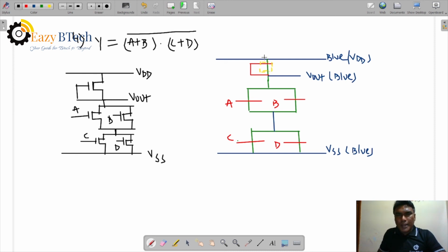Now let us take the contact area. Here is the interconnection point. Here also polysilicon and metal is an interconnection point. Both diffusions are interconnected. Metal and diffusion here, metal and diffusion over here in the series connection, and here also metal and diffusion. The ground metal and diffusion is here. So these are the logic. As per the logic, you can draw the circuit diagram in NMOS inverter, and you can draw the stick diagram. Then tomorrow we'll see the CMOS logic inverter and stick diagram.